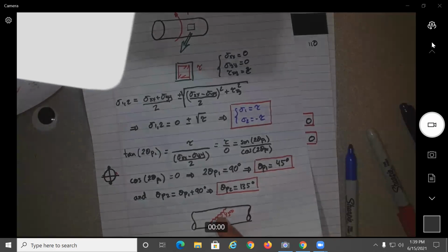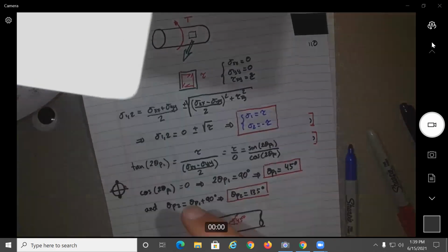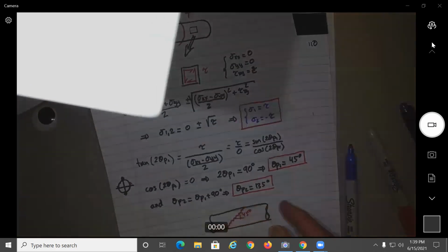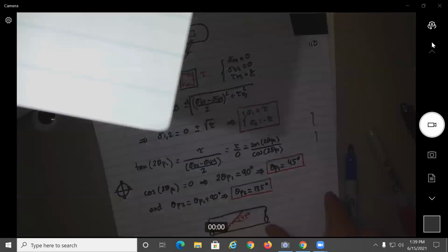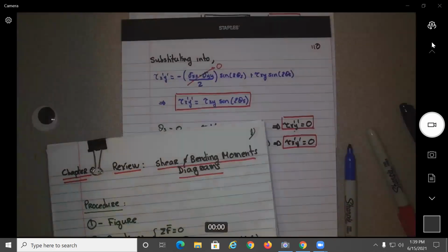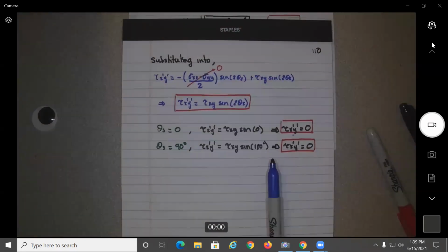Okay, and we say it's because when you apply the twist, it's as if you shorten or elongate the piece of shaft, and then it will create a normal stress. So if this breaks due to normal stress, it cannot break due to shear. So if we use the maximum shear stress theory for the same problem, it should give us that it should not fail in that mode. And this is what we get here. So this is basically confirmation